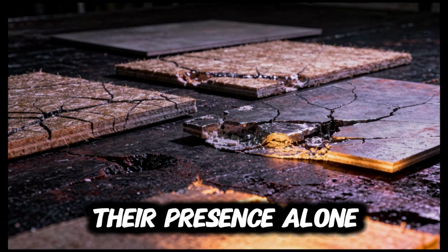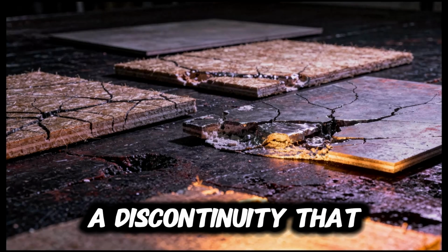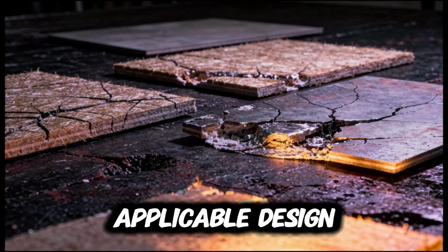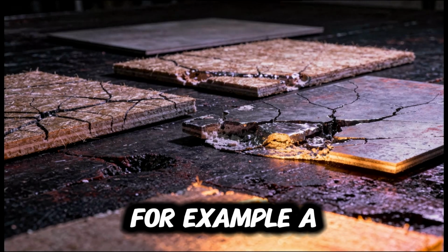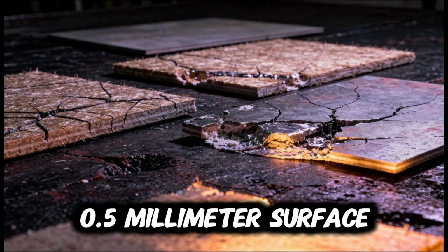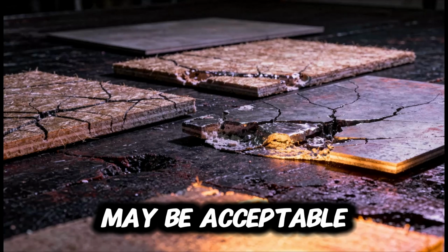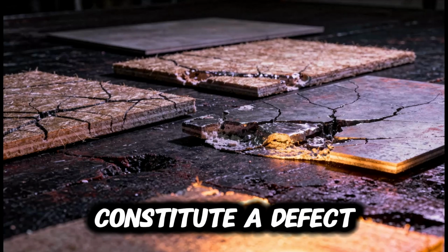Their presence alone does not imply component rejection. A defect is a discontinuity that exceeds the acceptance criteria established by the applicable design code, specification, or engineering judgment. For example, a 0.5 mm surface pore in a non-critical bracket may be acceptable, while the exact same pore in a pressure boundary component could constitute a defect.